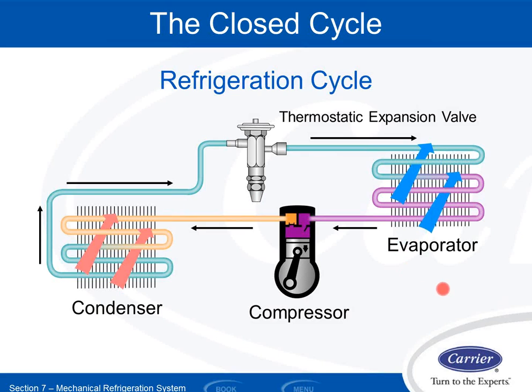So I said before, if I want to dehumidify the air, I got to blow it across the evaporator coil and let it condense out of the air, right? But then I call this the evaporator coil. It seems kind of weird from someone who thinks about things from an air side standpoint. But from a refrigeration standpoint, and by the way, all the HVAC systems evolved out of the refrigeration industry back in the day, from a refrigeration standpoint, the refrigerant is evaporating over here. And the outside, where he's rejecting heat, the refrigerant is condensing.